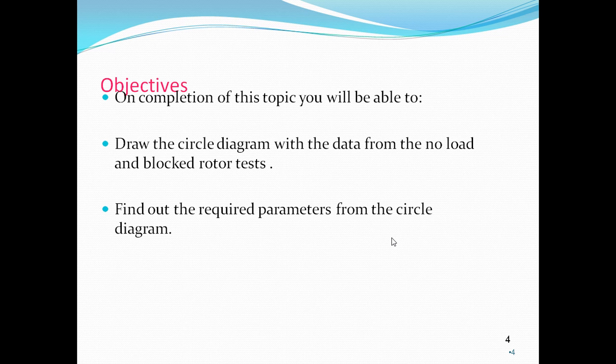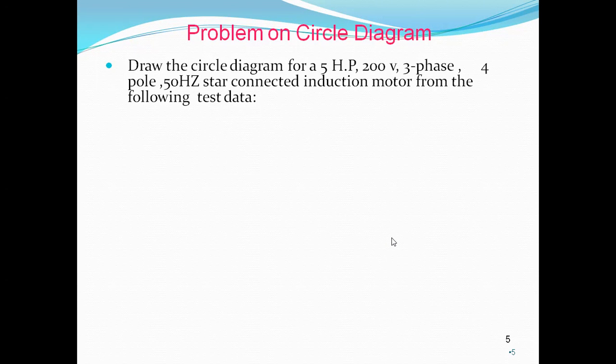how to draw the circuit diagram. So to draw the circuit diagram, what parameters we require, that is which test results we require, that is no load test and blocked rotor test. From these parameters, how we can calculate the required values, we have covered that. So today we will see some problems on circle diagram.